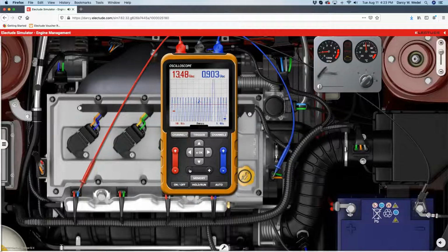And if I want to zero that in, here again, if I get it too high, it's gonna skip across the screen. If I get it just right on that pattern, it kind of zeroes it on the screen. And then I can also move it to the right or to the left. So just like a real lab scope, you can adjust those triggers to get just what you want to look at. A very nice feature for analyzing scope patterns and that sort of thing.